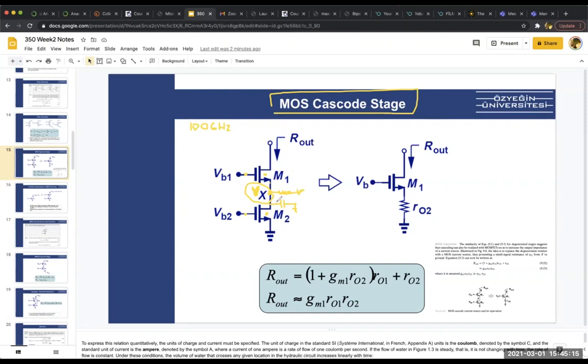So now there's a cap here, there's an inductance here. You learned, I hope, in 202 that this is a tank. A tank is just like the name. It might be dangerous. Why? Because this is a resonance circuit. At some point, when we look at the output versus frequency, you'll see something like this. And if you operate this circuit at this frequency, let's assume your current source or your voltage source, doesn't matter, you have a source operating at this frequency. And now it hits this tank. Well, what happens at this output?